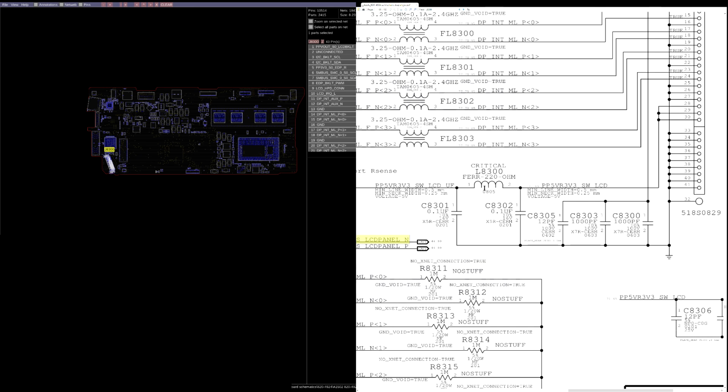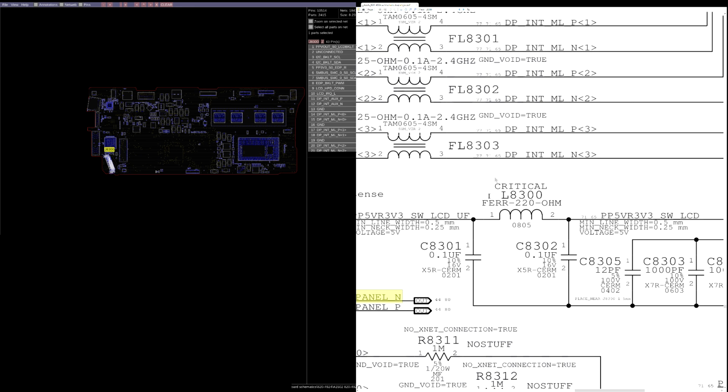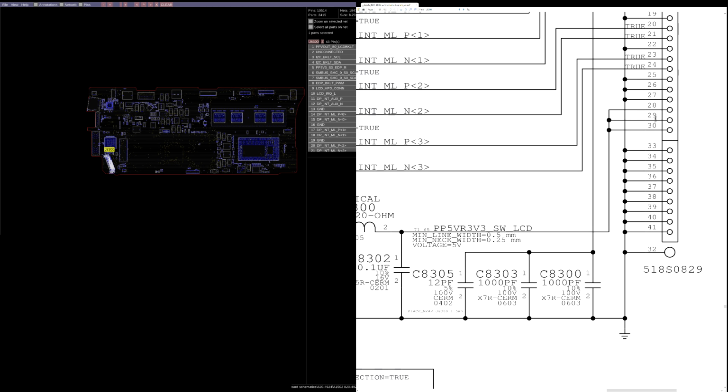So if somebody plugs something in improperly or there's water, it'll blow rather than the computer blowing up. And secondly, it's also going to slow the initial flow of current because the LCD takes up a lot of current and you don't want to blow the circuit or torture the computer. So this slows it down a teeny tiny bit. So on pins 28, 29, and 30 over here, I'm going to measure that and let's see what voltage we get on pins 28, 29, and 30. As you can see here, we're getting 5.1 volts, which is close enough.